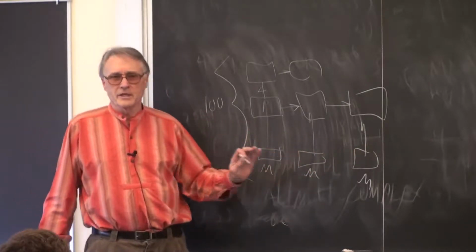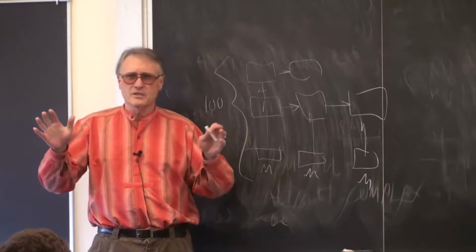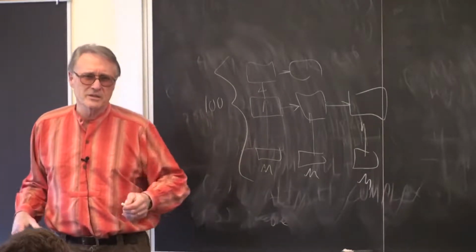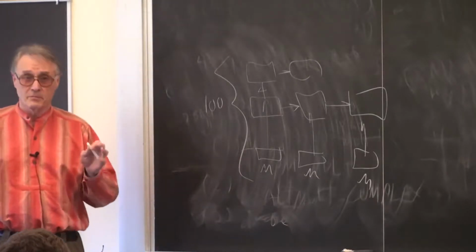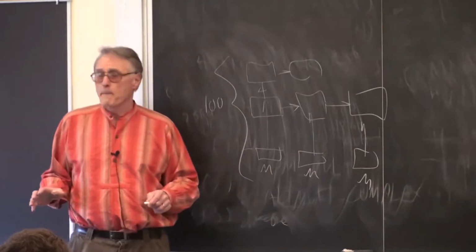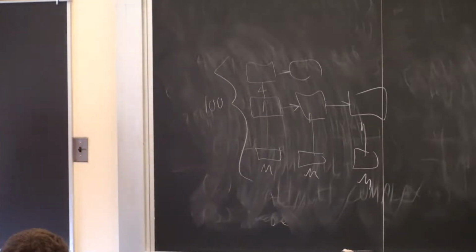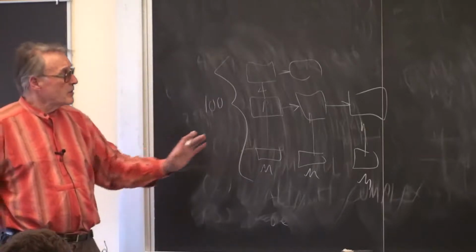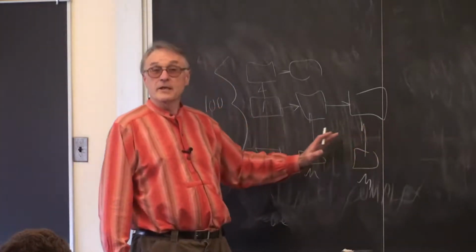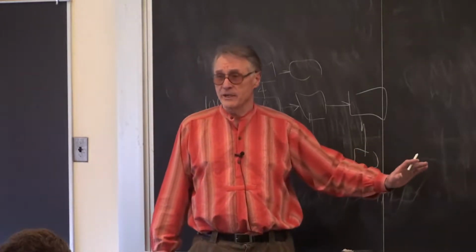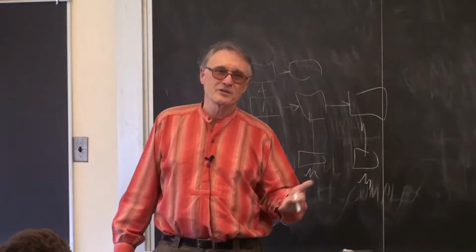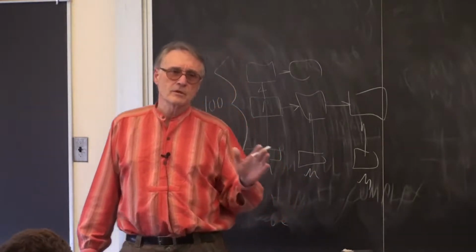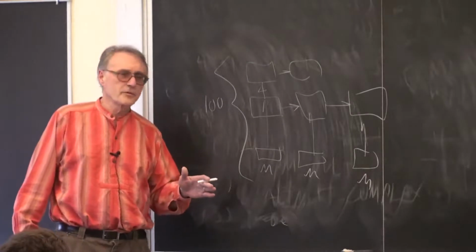You can try and fill in the details. Like I say, there's a couple of boundary conditions that have to be met. So there's some multiplexers that have to say nearest neighbors are either boundary conditions or they are other cells. But that's a detail I'll talk about. There's another topic I need to talk about, and that is we're making copies of stuff. That's error prone, and so you're going to want to use a generate statement, which is a Verilog construct that generates Verilog. So I'll talk about that a little bit next time too.